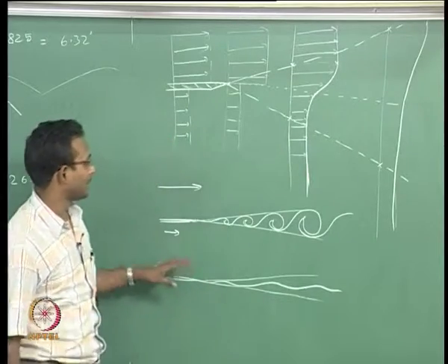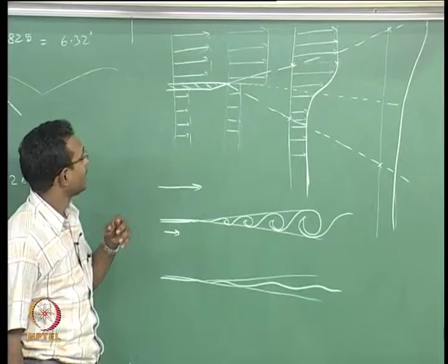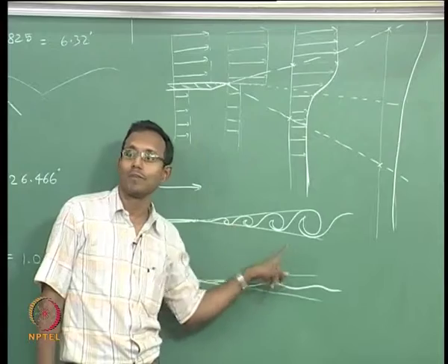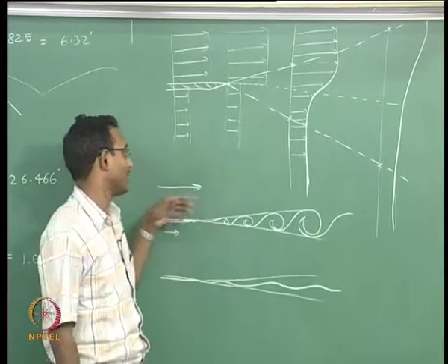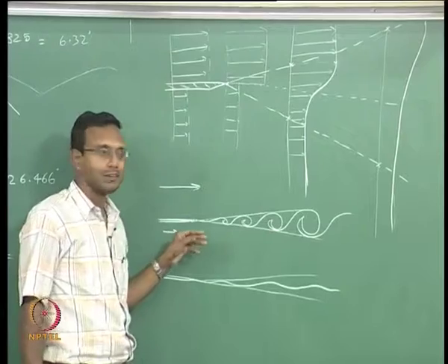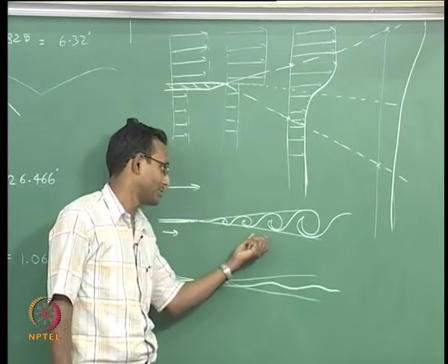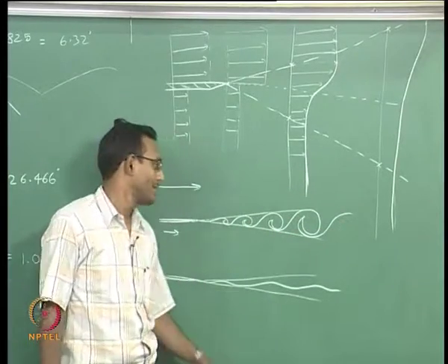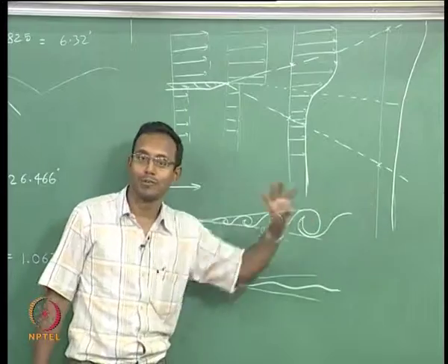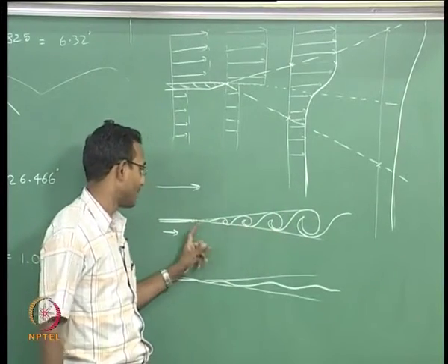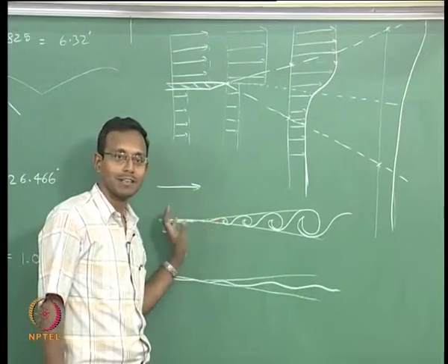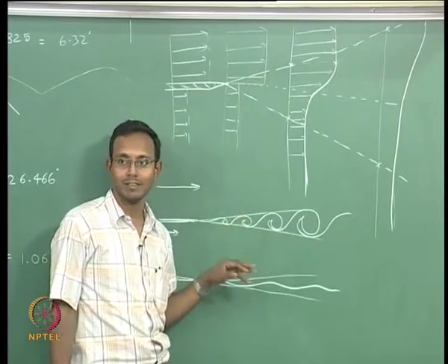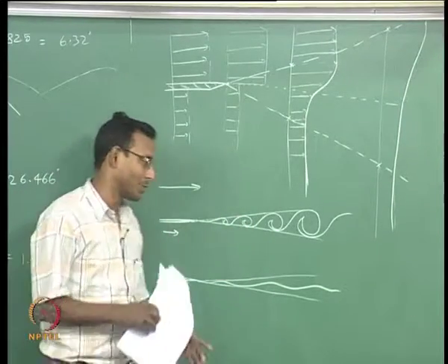We will now think about compressible shear layers, and particularly I want to talk about cases where large scale structures are formed. We will pick such a case, where one stream is going extremely fast compared to the other. Then I am going to form these large scale structures, typically some rotating eddy like structures. They are just going to be rotating as they are moving forward. When this one moves forward to become this, there will be one more coming from here to form something like this, and it just replaces every now and then. There is a particular rate at which it is going to be shed. There is so much to it, we won't talk about all that here currently.